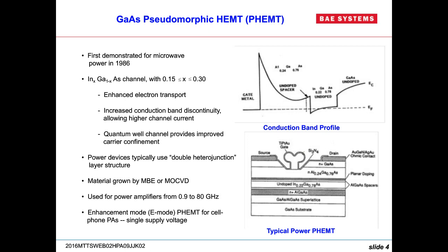The key to this is you think of it as sort of a designer's profile FET, that rather than a uniform structure, you've got a heterostructure with built-in layers that give you some advantage. In particular, you have the InGaAs channel. And typically the indium percentage is between 15 and 30%. Most of the processes are 25 or push the percentage up to 27%.